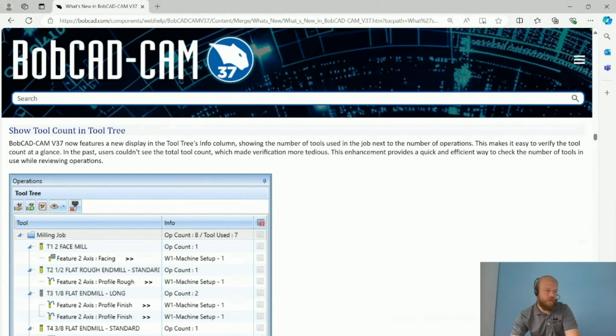Oh, Andrew, thank you for mentioning that. With the advanced holes, it used to be points only. Now you can select arcs as well for the advanced hole making. That makes sense. Yeah, and then you can create your 3D geometry, your counterbore, your thread, your hole, all of those settings in the advanced holes from any arcs now as well.